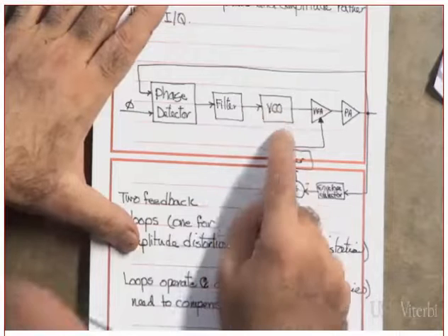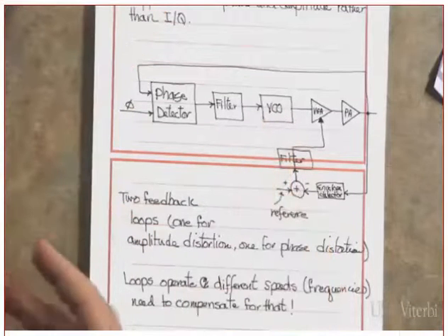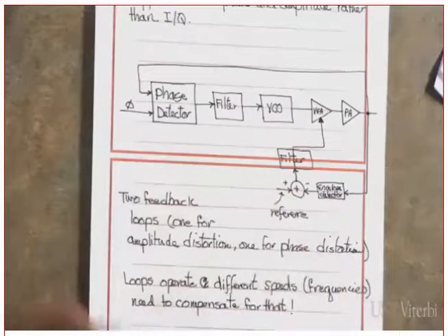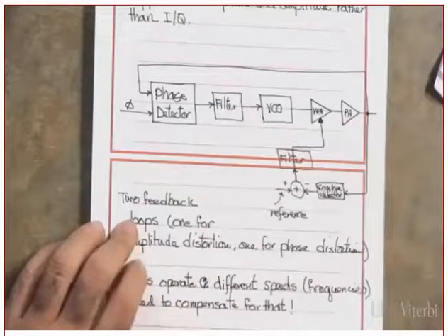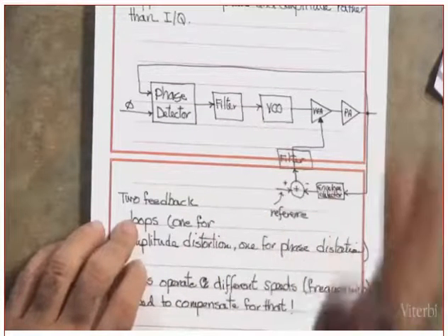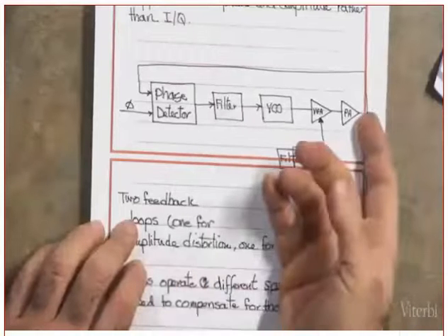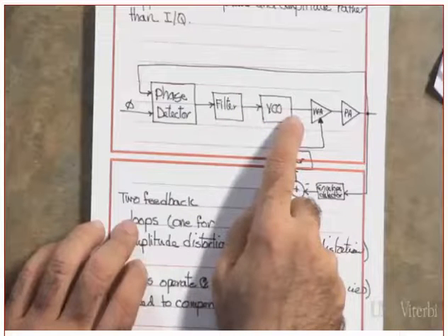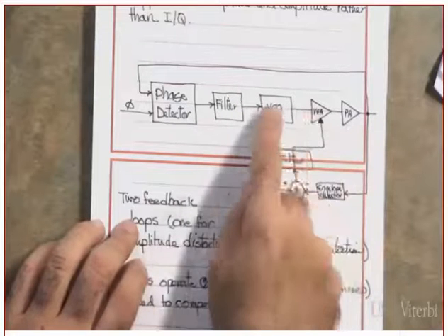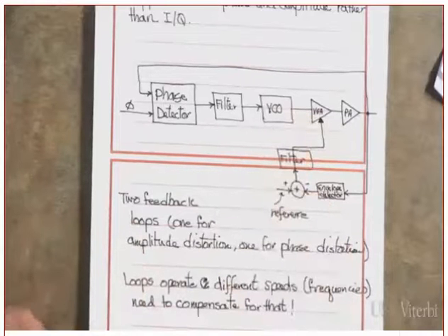A voltage we'll talk about this in detail shortly. The VCO is a device in which the output frequency is controlled by an input voltage. Is the input slowly changing? In other words, does it look like almost a DC? Almost a DC. Why? Because this is a low-pass filter. This is a small changing thing. It will change the what? It will change the frequency. The frequency of what? When I say VCO, what is this frequency? That is the carrier frequency. Did you get my point or not?